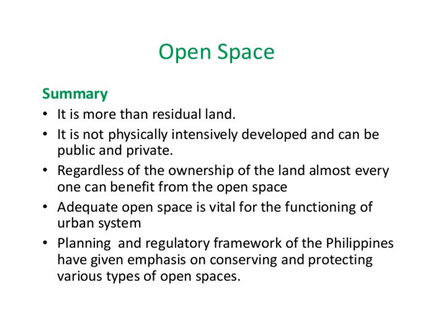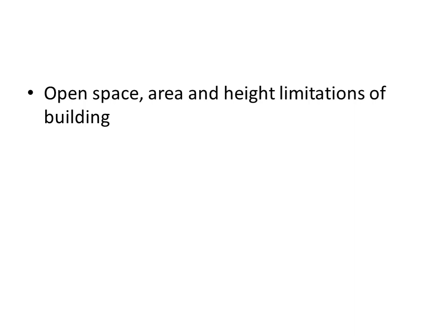Generally, in case of residential layout, generally 10% open space has been provided whenever the sanction of layout or subdivision is done. The exterior open spaces at the front, side and rear of the buildings depend upon occupancy, plot size, nature of development, maybe row building, semi-detached building or detached building, and width of road fronting the plot. The locality shall be given in the appendix.